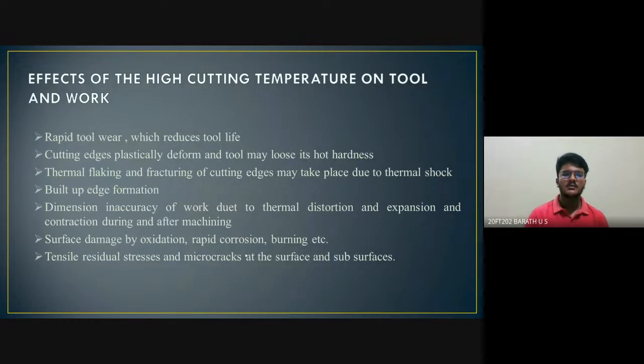Next, what effects are created by high cutting tool temperature on the tool and workpiece? It causes rapid tool wear, reducing the tool life, and cutting edge deformation, and it will lose hardness. When you increase the feed and speed, the tool gets highly heated, and the heat damages the hardness of the tool.